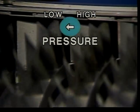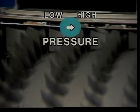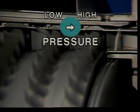At each stage, the rotors increase air velocity and the stators slow it down. The energy derived from slowing down the speed of air results in a slight increase in pressure. While the velocity of air remains almost steady, the pressure is increasing as it passes through each stage. Each stage multiplies the pressure obtained from the preceding stage.